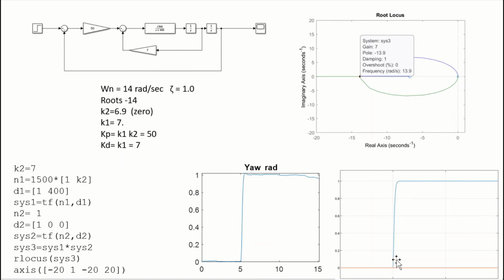And if we look at the simulation now, it is critically damped, and this is the drone running, and this gives very nice performance. Interestingly enough, with a critically damped design here on the drone, its X and Y movements are much less, indicating that for a drone you really want it critically damped. This gives you a better overall performance than, say, going for a damping ratio of 0.6 or 0.7 as you might in a normal flight control system.